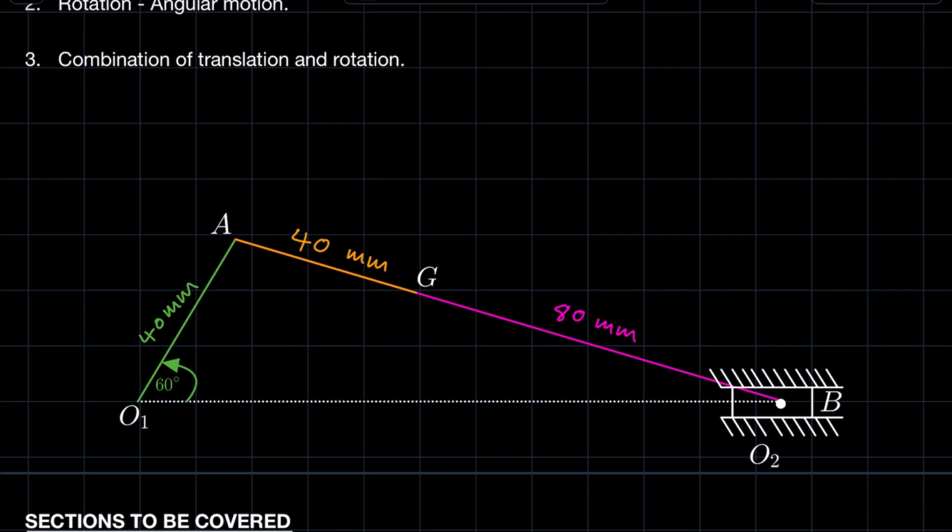If we have to calculate the velocity of a rotating link, then we have to find its tangential velocity. Its tangential velocity will be perpendicular to the link. Why perpendicular to the link? The link represents the radius, and the radius of this link is its length. So each of these links we are able to take as the radius of the link itself.